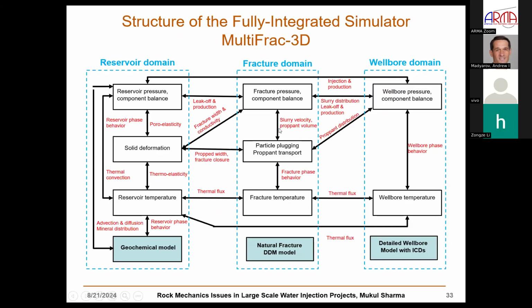So to model all this, in the last 10, 15 years, we've actually built a simulator to model not just this process, but also hydraulic fracturing, and certainly capture the flow and the geomechanics. This model is modular in the sense that it has a reservoir domain, a fracture domain, and a wellbore domain.